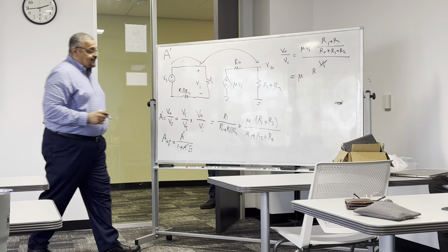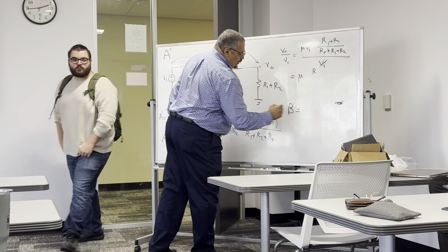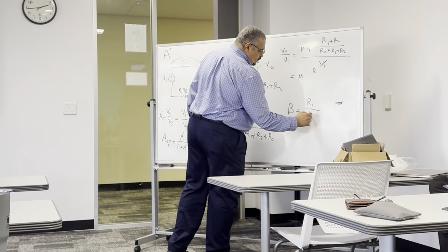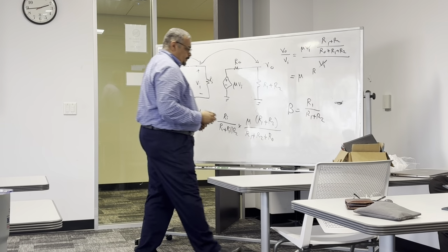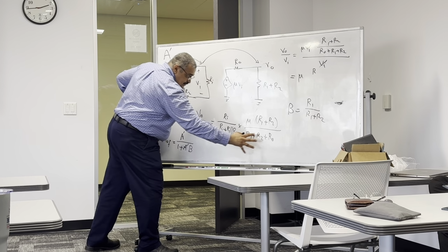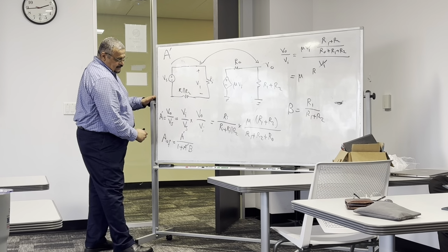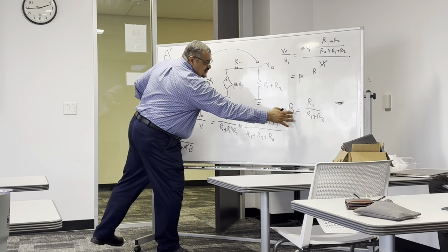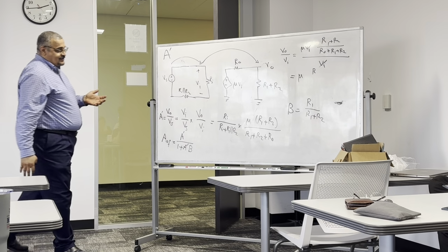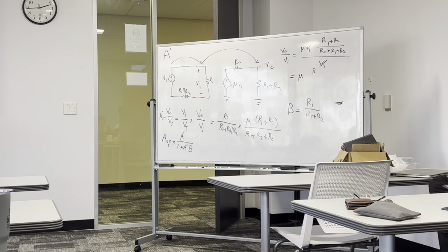Now the question, what's beta? I think we did it many times, so beta is the voltage divider. So it's R1 over R1 plus R2. Okay? So all what you need now is to take this, plug it in here, here, and you take this, plug it in here. So the equation is going to be very large, right? This is why I didn't include it here, but you have to take this, put it here, and again put it here, and then beta, which is this one.